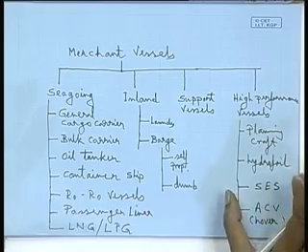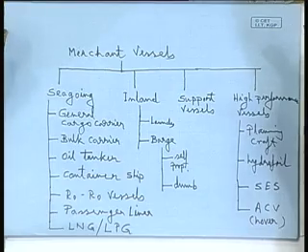What is the difference? Why have I classified them as separate? Well, because they are high performance. What does it mean, high performance? Speed is a relative term in the case of ships. We talk about the speed length ratio, V by root L, that comes from the Froude number, V by root gL, g being a constant. Depending on the length, for a given speed, it may fall in the high speed zone and be classified as a high speed vessel.